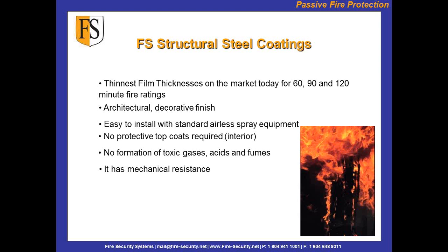No, regardless of application or where it is, I would always wait that 30 days as a full cure time. I mean, it's tack dry in 24 hours, and within 48 hours, it's got a skin on it. But if you're looking at 3 or 4 millimeters in dry film thickness, you've still got a period of time where that thickness under heavy coat has still got to cure out. So you've got to let it get to its full hardness, and 30 days is its full hardness.